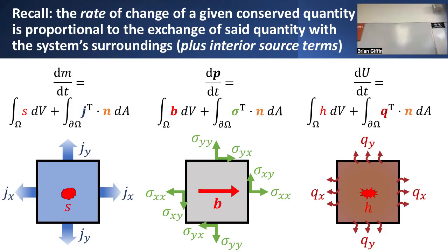I can arrange them in this way where I might have, let's say, an x component of traction, or basically a force per unit of area that acts in the x direction, but which acts on some x-directed face. And I might have called that sigma sub xx. I could go through and define all these different components of stress. I could organize them into the format of a 3x3 array if I'm looking at a problem in 3 dimensions. And another word for a 3x3 array is just a rank 2 tensor.